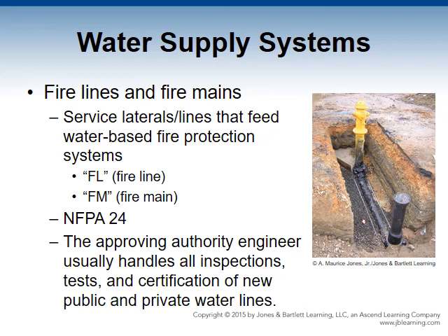In new installations, the water company or contractor taps into a distribution line and then installs a control valve and enough piping to reach the property line of the project where the line terminates. From the termination, the developer might install distribution mains and secondary mains for the domestic water lines, and fire hydrants within the development site.